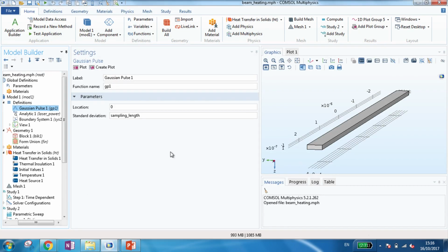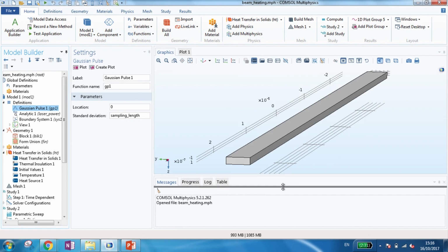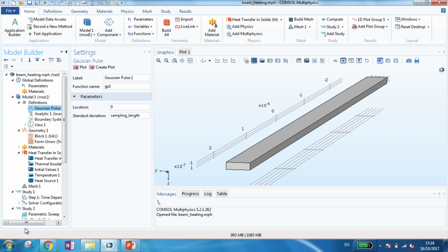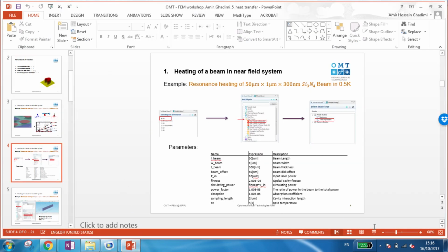So you start with the COMSOL Wizard, you go to 3D, and previously from this morning we were talking about structural mechanics, right? Now we're going to use another package here. Inside heat transfer, you have a physics study called heat transfer in solids. Use that, and when you select that, there are two types of studies you can do: stationary or time dependent. And we're going to do both of them.